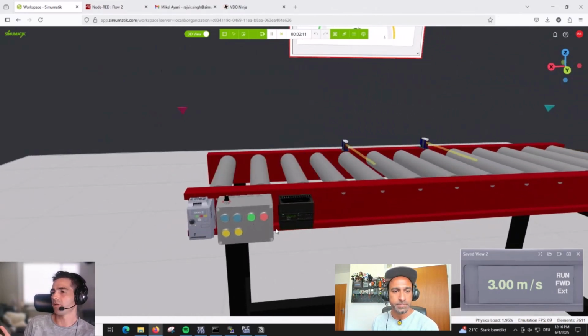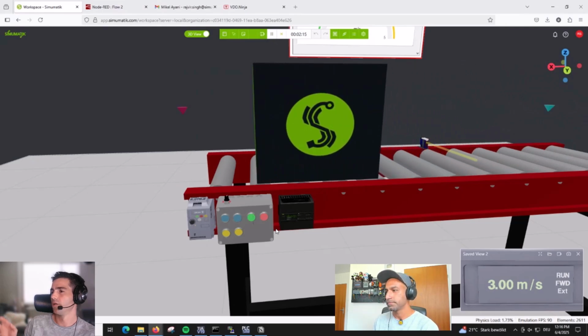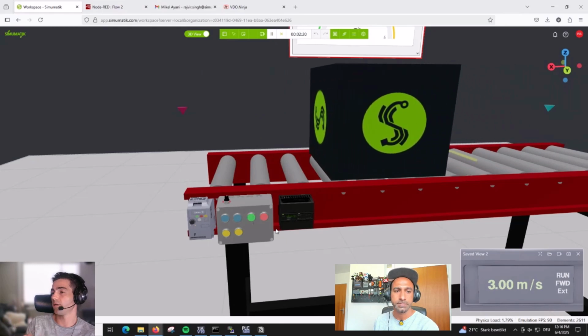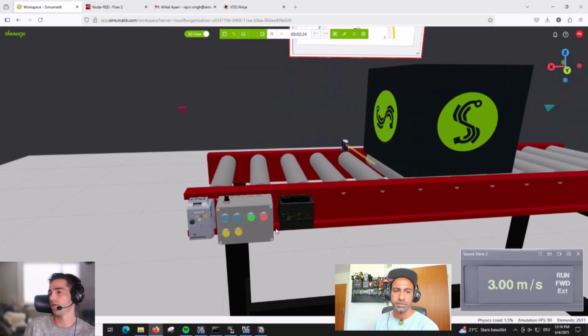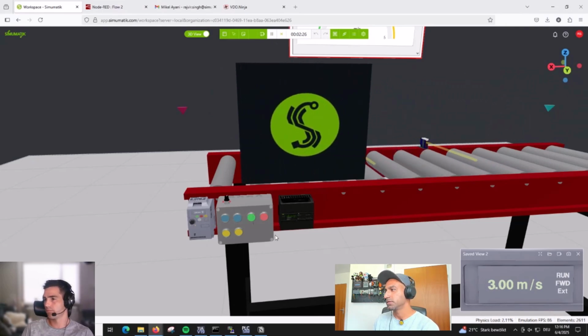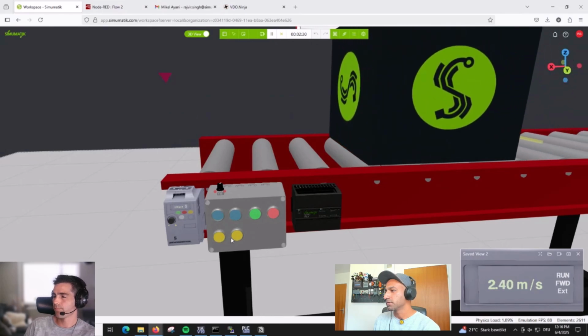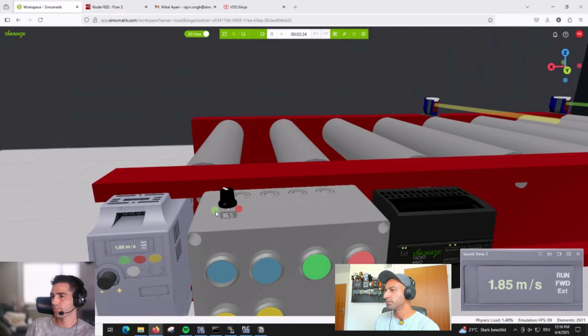Okay, so 2 buttons, 2 digital inputs. You can select between no set point, using the potentiometer, or set point 1, 2, or 3 when you press both. It's basically binary to decimal, 0, 1, 2, 3. So when I turn both of these off, then it will follow the potentiometer. So different ways to control.